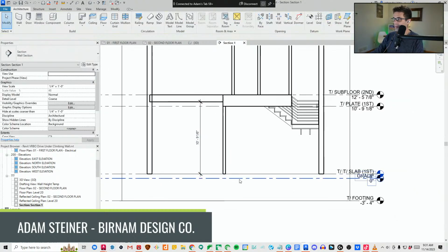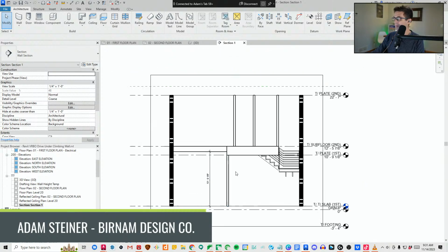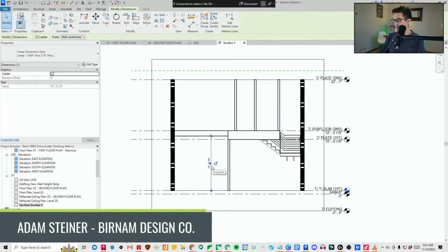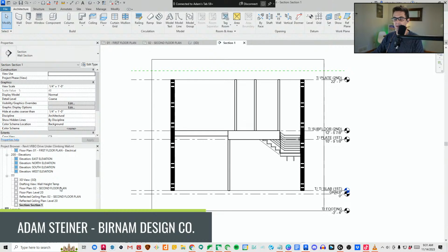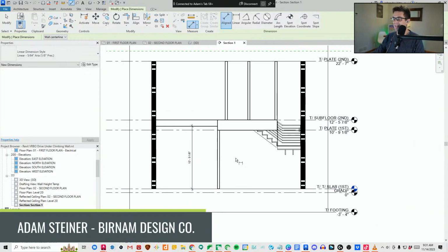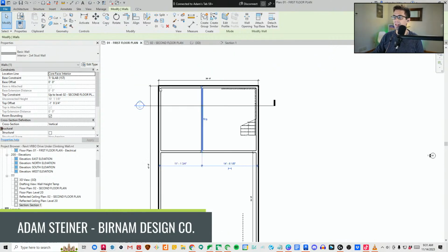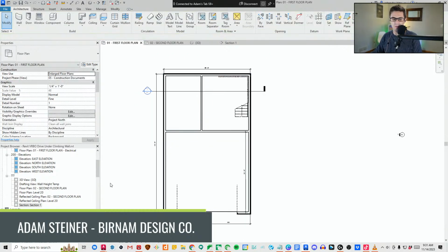I could go more drastic if I wanted, but I'm not right now. That's pretty good for a bouldering wall in that space. 10.9. Yeah, that's awesome. And just make this a bearing wall. Can still be 2x4 because it's only carrying one floor and roof. Or I mean, it wouldn't even be carrying roof because we probably do trusses if we're gonna do floor trusses. So yeah, it could be a 2x4 bearing wall. That would be fine.